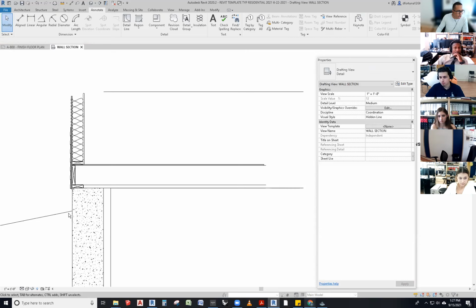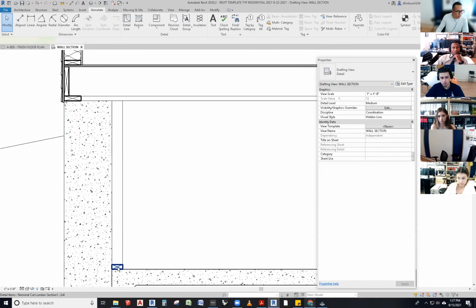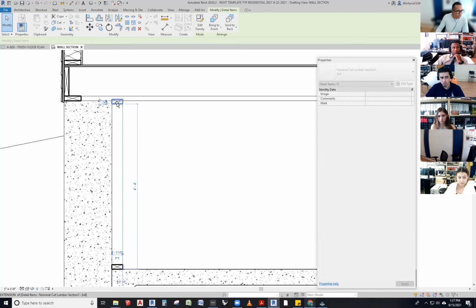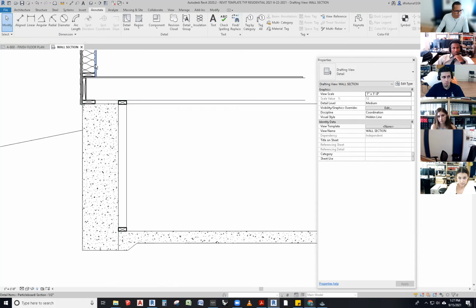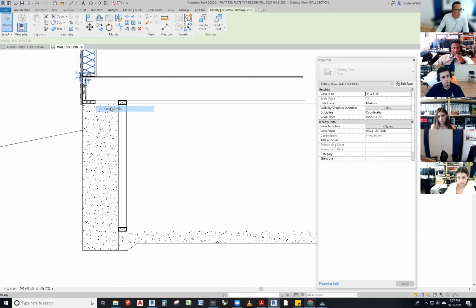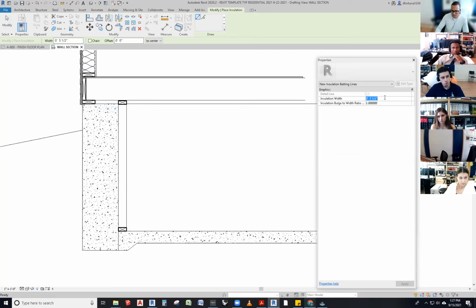So this basement is not necessarily finished. To finish it, we need a top plate here also, which may go like that. We also probably will put insulation inside, which will not be 5.5 inches because we're not using a 5.5 inch stud. Oh, my bad, that was big. 3.5 inches, my bad. So that goes in here, your insulation.